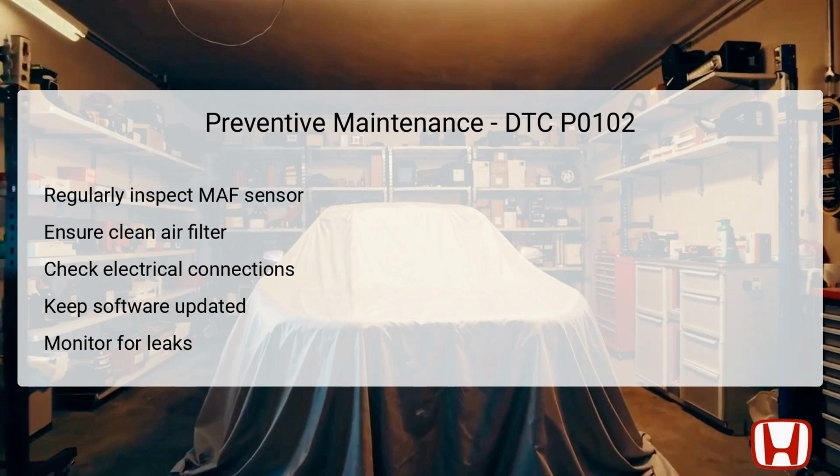Keeping the PCM updated with the latest software can enhance data interpretation and compatibility. Lastly, consistently monitor for air leaks in the intake system, as this can also affect sensor readings and overall engine performance, helping to prevent premature failures.